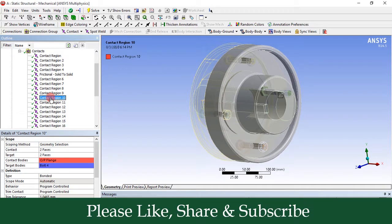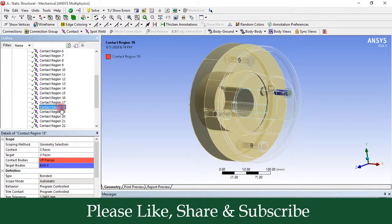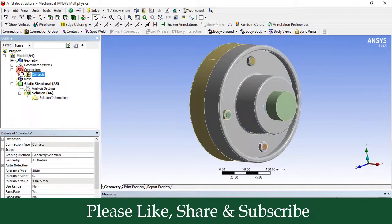This is contact between output flange and bolts, output flange and remaining bolts. In this way, other contacts are taken as bonded. Here you have to remember only one point for this type of contact: contact between output flange and input flange is taken as frictional type of contact, others are bonded type.